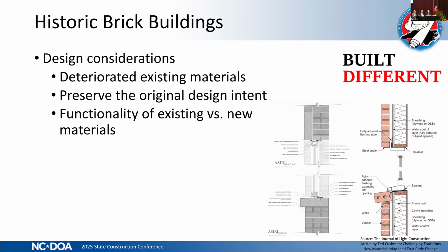You cannot prevent the exterior bricks or mortars from allowing the moisture to be absorbed and then evaporated. Do not seal these walls. Review the history of the building. Has it undergone any major renovations over the years? Was it previously painted? Has there been any long-term exposure to heat or water?